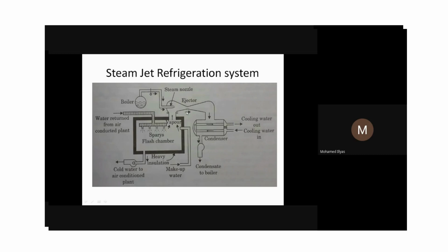When the steam expands here, suction will be created, so that low pressure refrigerant vapor can be taken. Both will be mixed. Mainly we call it a mixed gas. So here we have a dual purpose refrigerant. We are taking low pressure vapor as well as taking away the heat, so we extract the heat. We have various kinds of refrigerants, like R12, R22, R134A, ammonia.